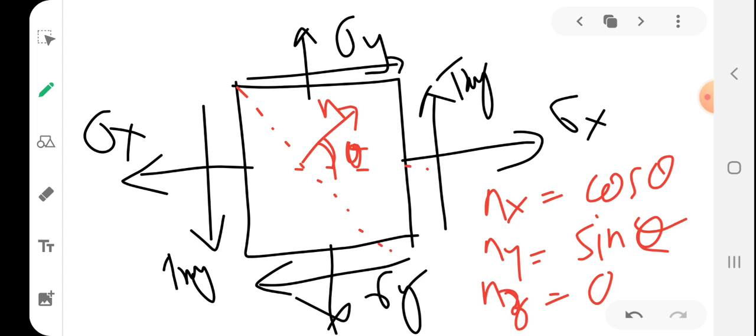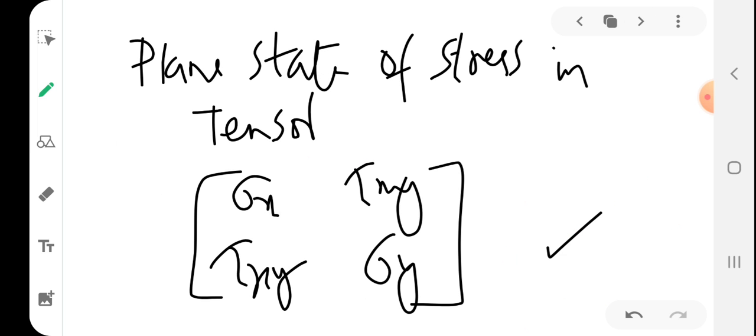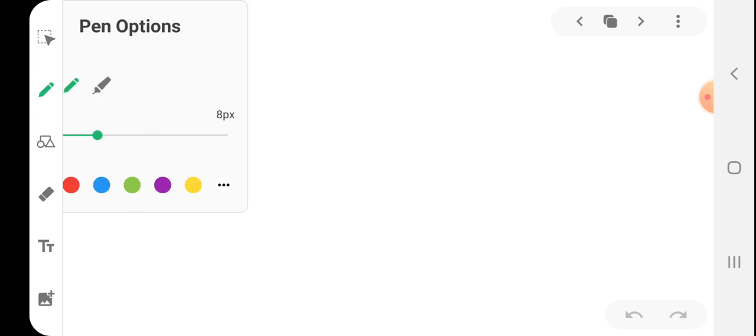So how to find the state of stress, or the stress components, in that particular plane for the same particular point? How can you do that? You have to apply Cauchy's equation, the same way we have done in the case of the three-dimensional equation, right? So you remember Cauchy's, right? How to write Cauchy's here? Suppose we have to find the t vector with n as the normal to that particular plane. So tx, the x component of t in that plane, can be obtained using what?